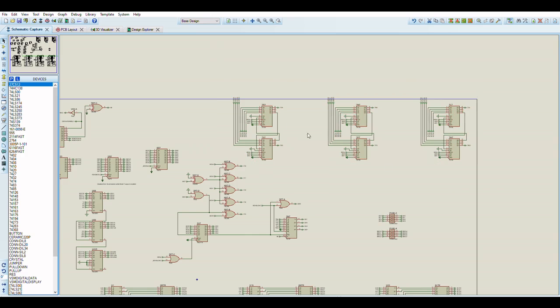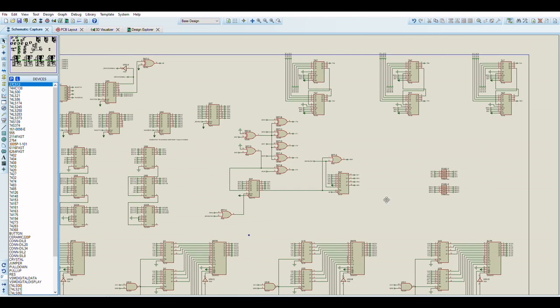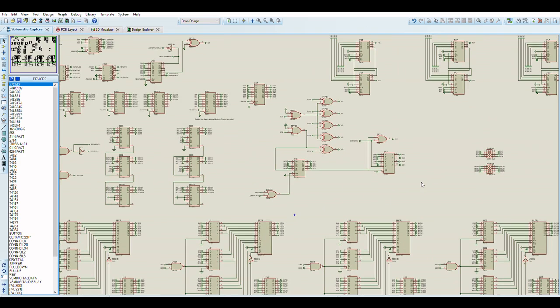So when it's rendering one tile, these will refresh 2 bytes worth of data for every 16 pixels that are output. The logic for horizontal and vertical flipping is the usual methodology that we would normally see.